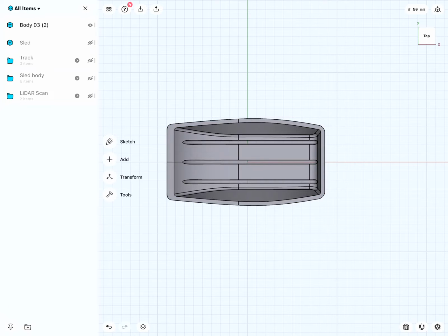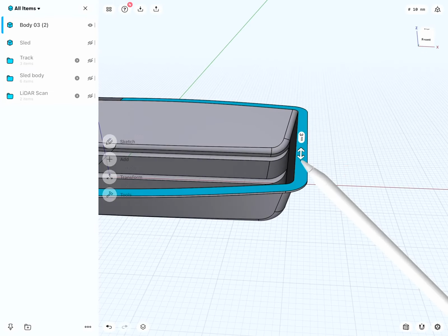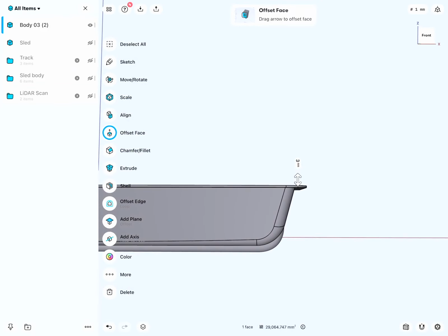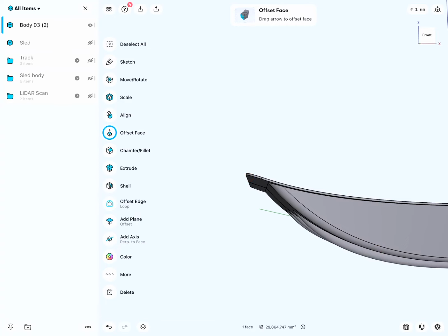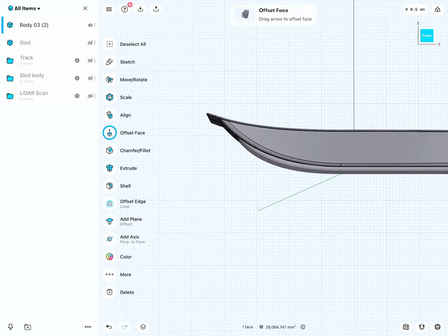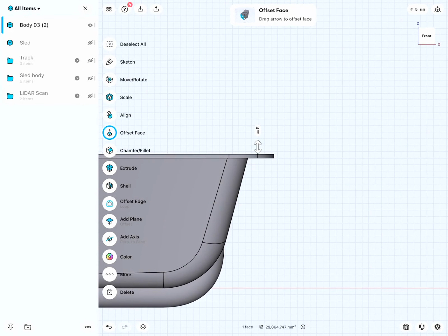For stability reason, this lip which we created, we want to fold down here a little bit, also there. So the whole construction will be a tick more stable. Also there I developed a neat trick to create this sweep surface and still end up with very clean surfaces.